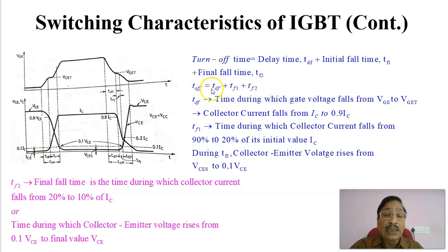What is the delay time TDF? During the turn off process, it is the time during which the gate voltage falls from VGE to the VGE threshold voltage.